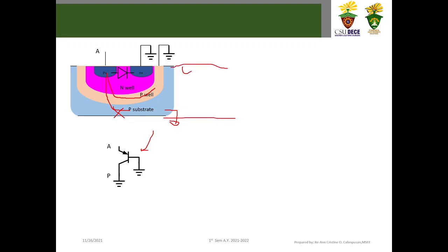So this would entail less noise and no effects on other circuitry, so it is isolated. This is a great configuration or arrangement for a BJT implemented in the CMOS process. With that, we can create a CTAT diode when we lay it out or configure it in CMOS.